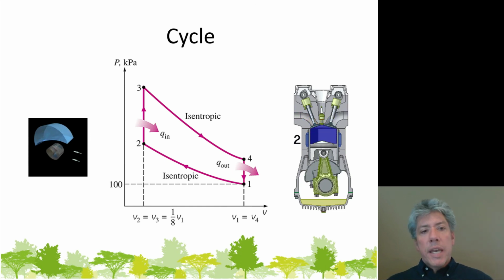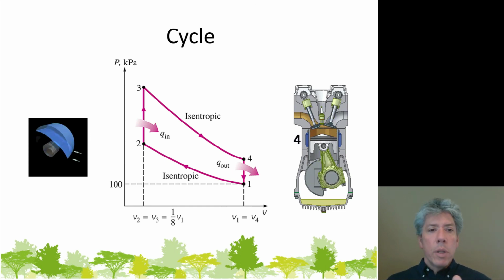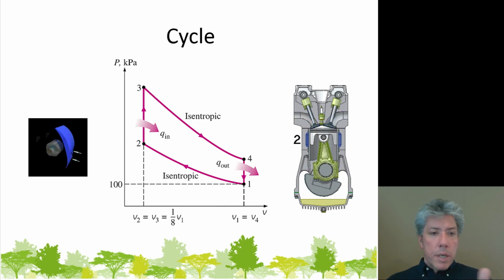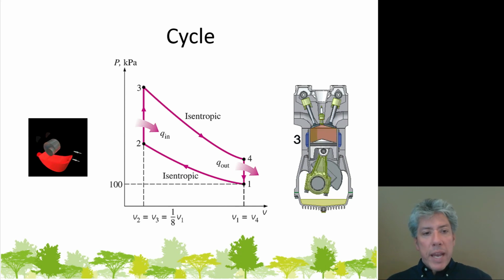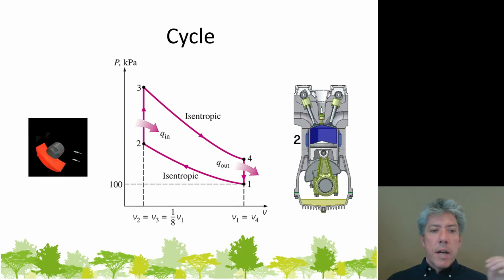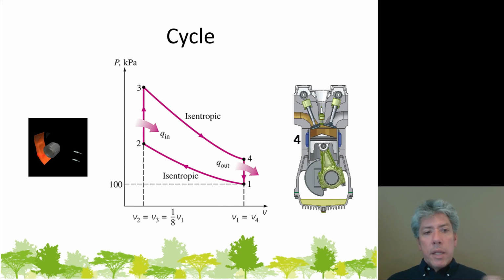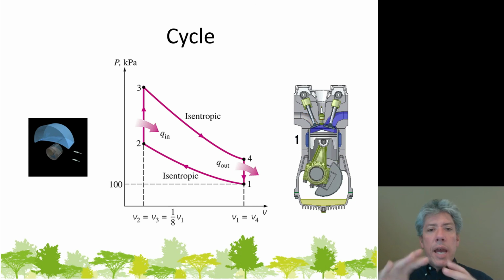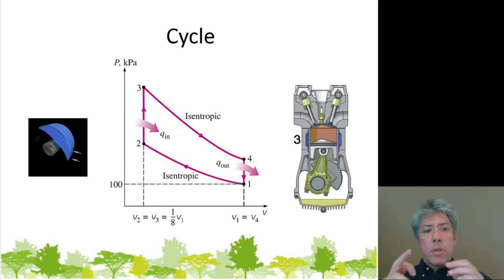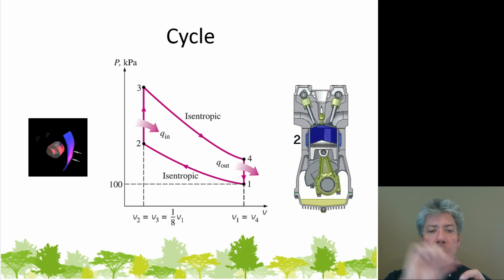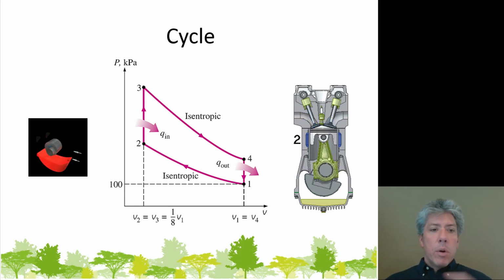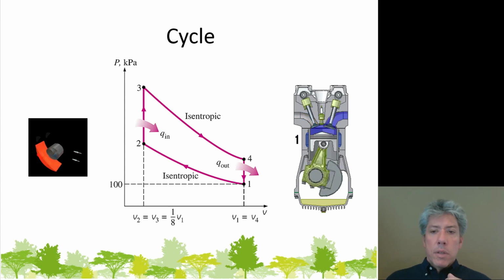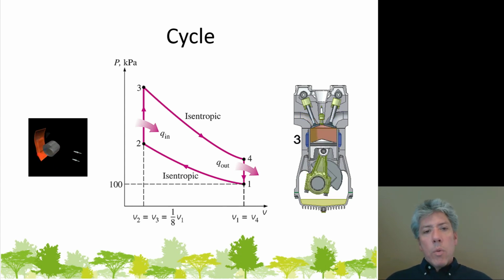And so we've got initially an intake of fresh air and fuel. We've got compression. Then the spark plugs light it up. Now we've got expansion, and then exhaust out the exhaust port, and then the rotor comes back around. Of course, what's interesting about a Wankel engine like that is that the rotor has three sides. And so those three sides are kind of like a piston on every side, where a different portion of the cycle is occurring. Well, we can actually analyze this, or even the typical piston cylinder cycle, with a PV diagram.